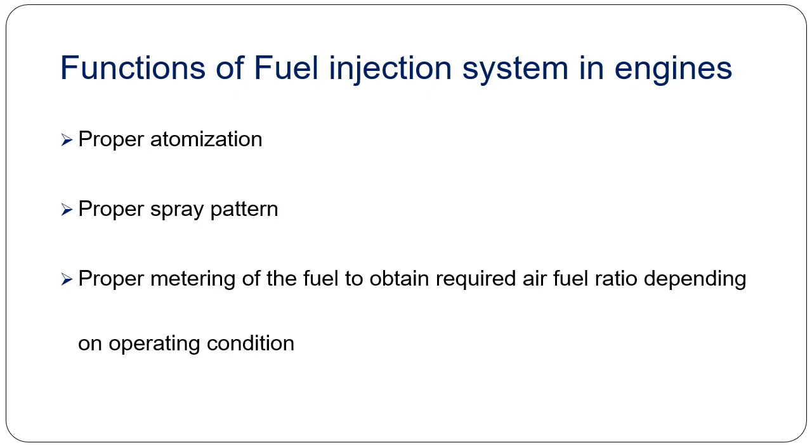And we know that for starting and idling and accelerating condition we need rich mixture, and during cruising range we need more fuel economy, so the mixture should be lean.